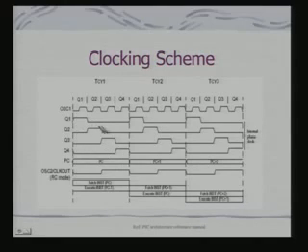So what you find here, just look at this. You have your first cycle where you fetch an instruction. Let us start with this. In this, I fetch an instruction. Now, once I fetch the instruction, I have shown it within the bracket saying PC. That means I am fetching the instruction which is being pointed to by the program counter. In the next clock cycle, I am actually executing the instruction that I have fetched.